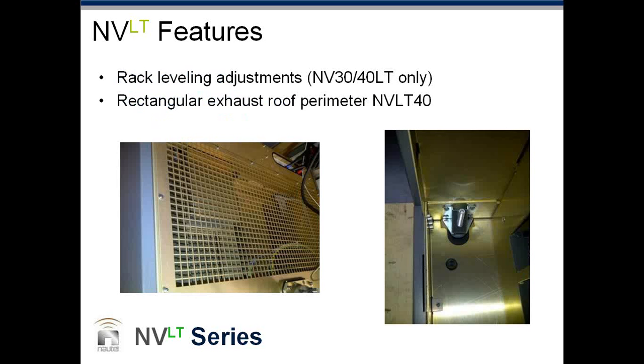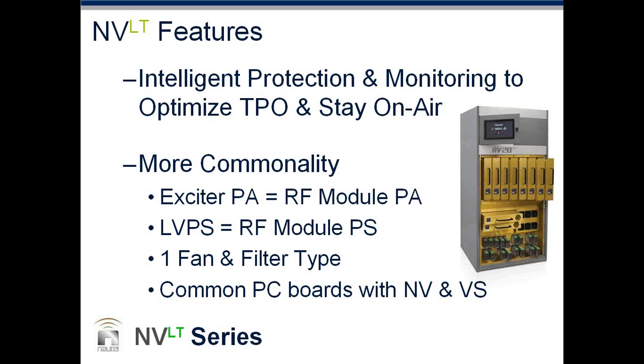Right. Okay. Again, looking at that same information, this one is a 20 kilowatt, again showing that the exhaust ducting is in fact rectangular and easy to connect to, and we've got leveling feet in the corners of the high-power transmitters because of the larger footprint of these. Because all the connections, all the modules and power supplies are blind mate, it helps to have a level transmitter to allow the mechanics to work properly. Sure. Okay.